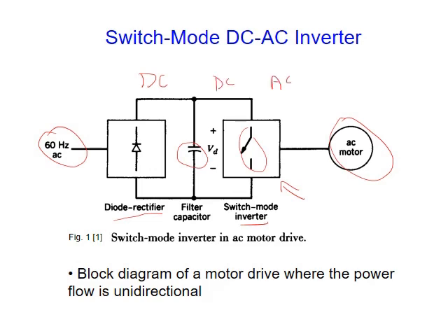You say, okay, what is the point? It was AC, you converted to DC and then back from DC to AC. Yes, correct, because this AC is not controlled. It's giving me 230 volt, frequency 60 Hz as an example, or 50 Hz. But at this point, I control the frequency, I control the voltage magnitude, and so on.